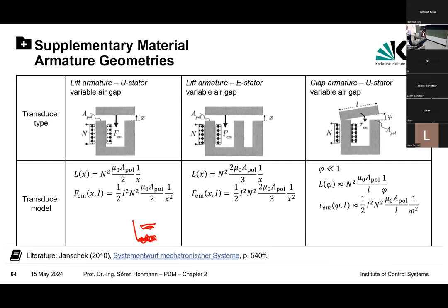And the interesting fact is that sometimes it's important that the combustion chamber remains closed. The start of warming-up phases, remember the emissions problems in the diesel engine scandal. Well, that's exactly that. When the car is warming up, you have different times when to open the inlet valve and when to open the outlet valve compared to the full high-temperature regime when the car has already driven 100 kilometers or so on the highway.